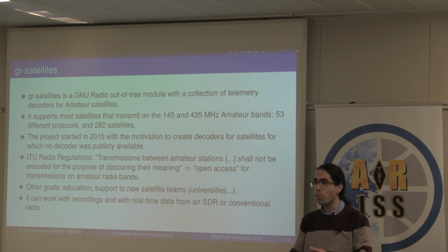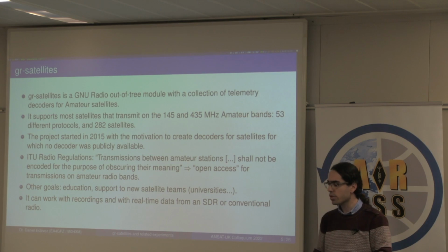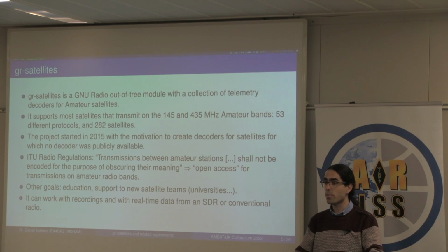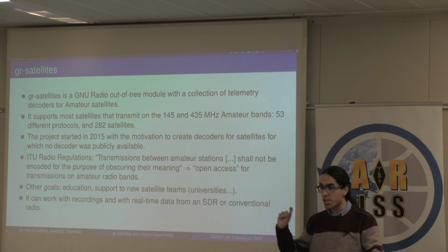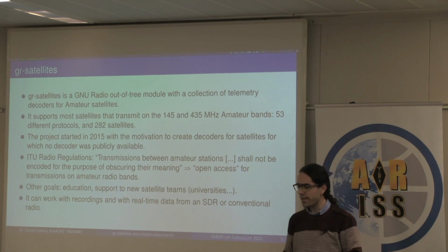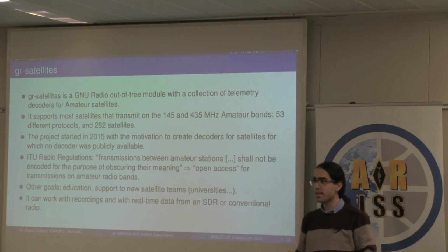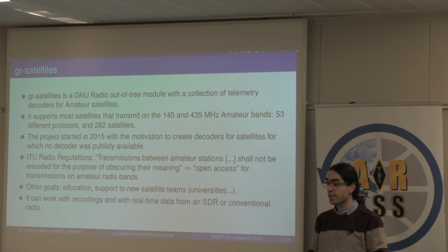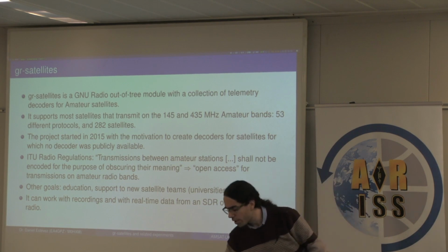Now that we have this open source tool to decode all these satellites, people who are working at universities, for example on university satellite projects, can go in there and study how everything works. And it's also good to support new satellite teams so they don't have to start again from scratch. They can rely on these, and maybe the satellite uses some new feature, but it's just this new feature they need to develop. And it can work as well with recordings you have done, so pre-recorded files, or real-time data you can stream in from an SDR device or a conventional radio. If you have a conventional radio, you can hook it up to the computer sound card and you go.